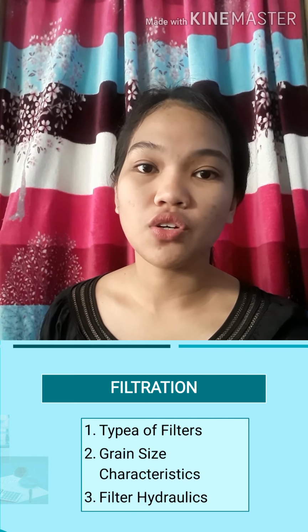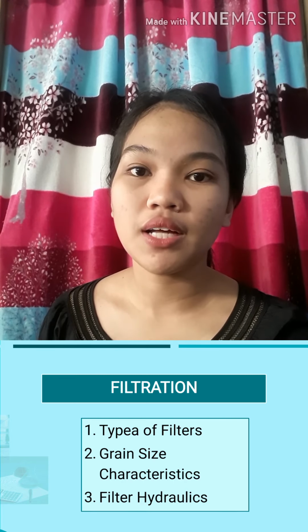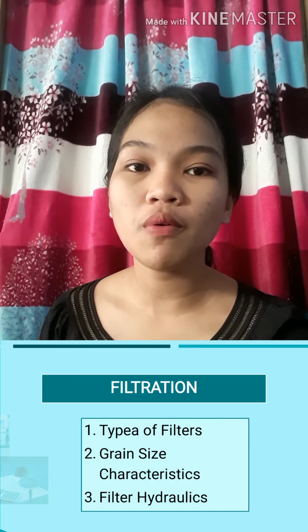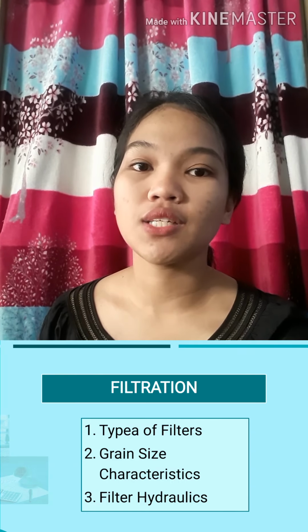So what is filtration? Filtration is most often used as a limiting step to remove floc and finer unsedimented particles through beds of granular materials. Filtration also removes suspended organic matter, microorganisms, and dissolved minerals from the water.